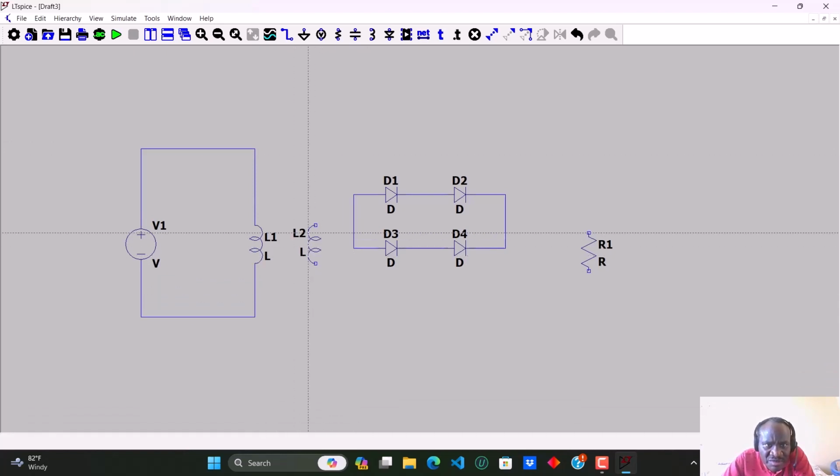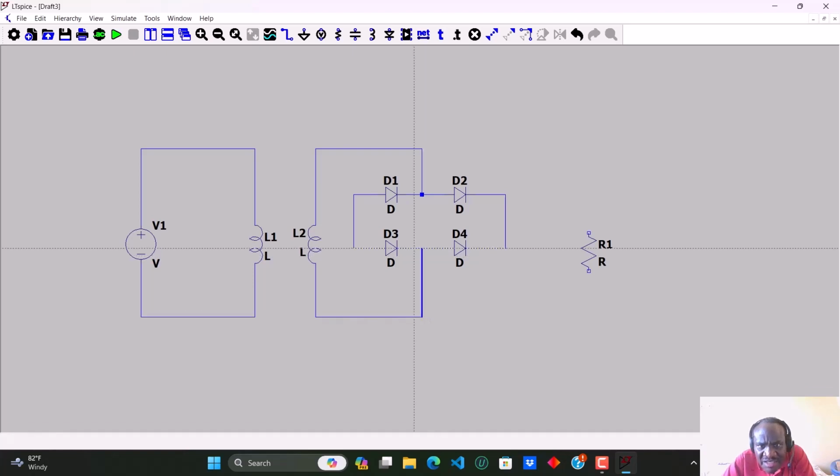This secondary coil of the transformer needs to be connected to this one here. Come here, click, move, click, connect it there. There I have it. You don't need to do it beyond. There it is. Then this other side, click here, click, go down there. I want to make it look nice. When it's there, I click. Then I go up here, and I click.